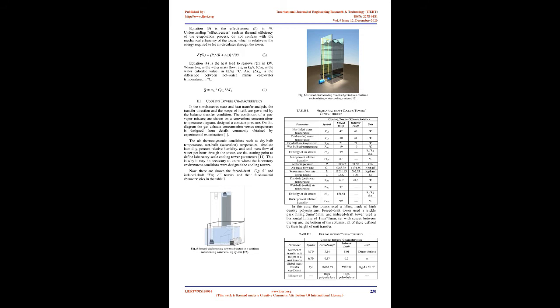The performance of every cooling tower, large or small, depends upon the quantity and thermal quality of the entering air. External influences which raise the entering wet bulb temperature, or restrict airflow to the tower, reduce its effective capacity. Air restrictions, recirculation, and interferences can be minimized, possibly eliminated, by careful planning of tower placement using the following guidelines.